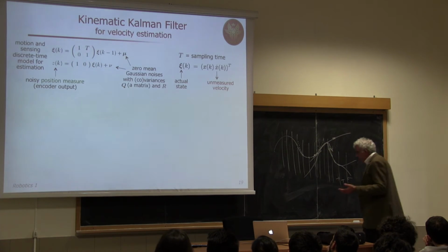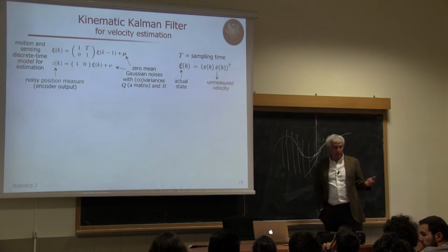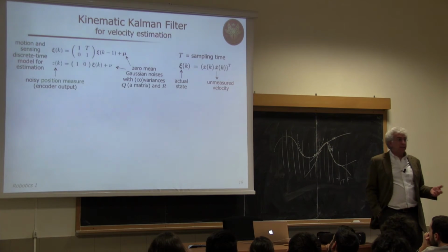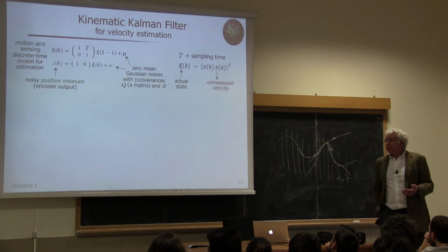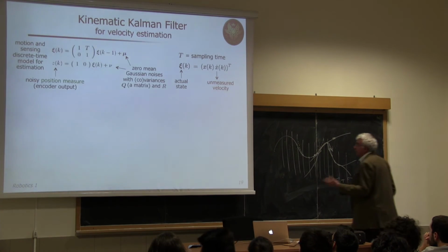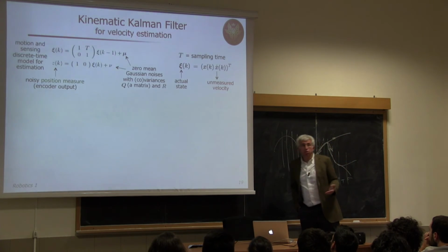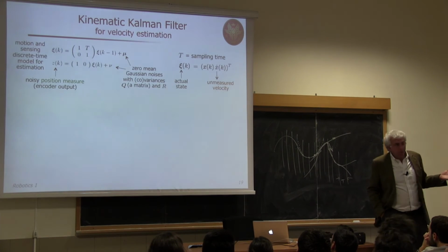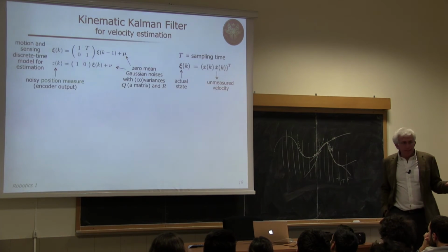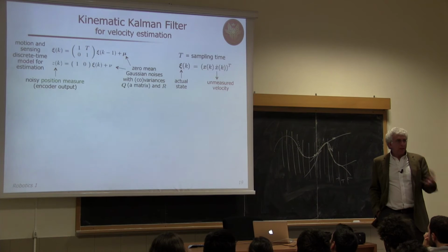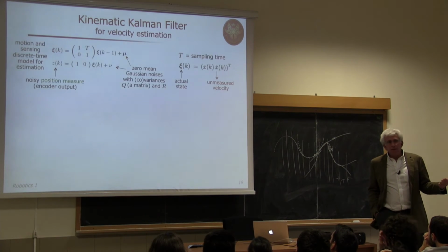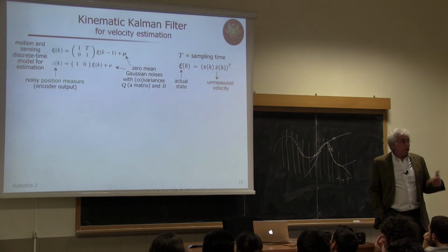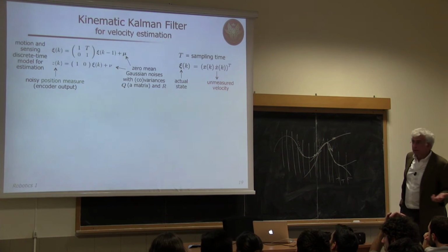And the Kalman filter for a linear system having linear dynamics, assuming that the noise is a white noise, a Gaussian noise with zero mean, it's optimal. So you cannot beat a Kalman filter under this condition. Linear dynamics of your process, so linear measurement corrupted by Gaussian noise.